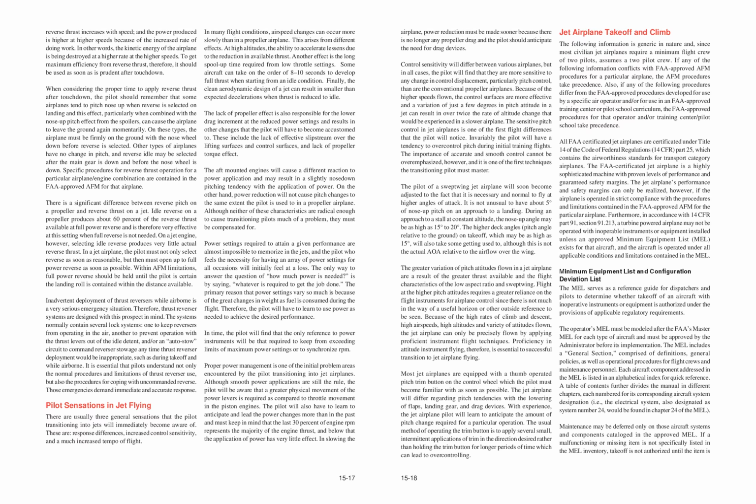These include the lack of effective slipstream over the lifting surfaces and control surfaces, and lack of propeller torque effect. The aft-mounted engines will cause a different reaction to power application and may result in a slightly nose-down pitching tendency with the application of power. On the other hand, power reduction will not cause pitch changes to the same extent the pilot is used to in a propeller airplane.